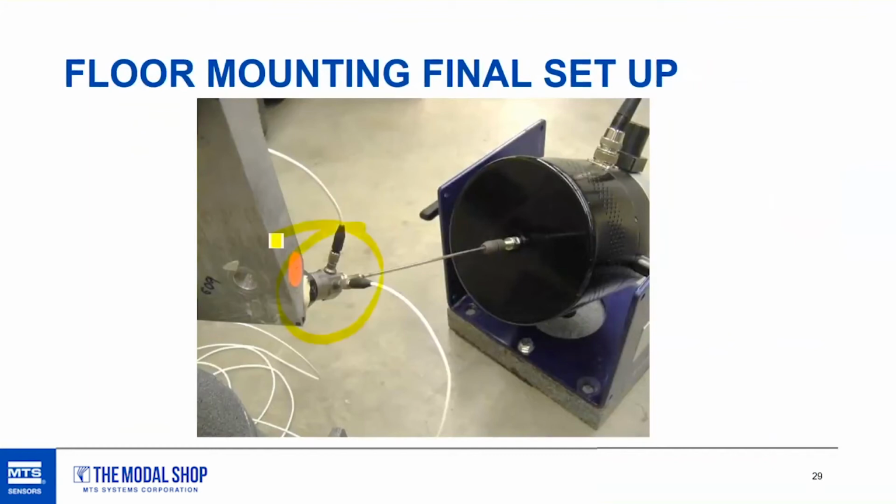My sensor was pre-installed on the structure using some dental cement. And one final touch here, some people like to apply a bit of hot glue where the shaker is sitting on the floor, so you can add some glue there so that thing doesn't move.